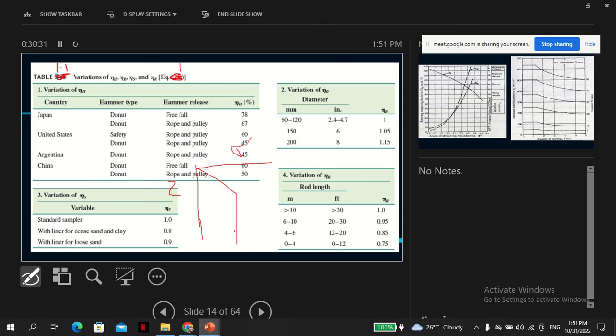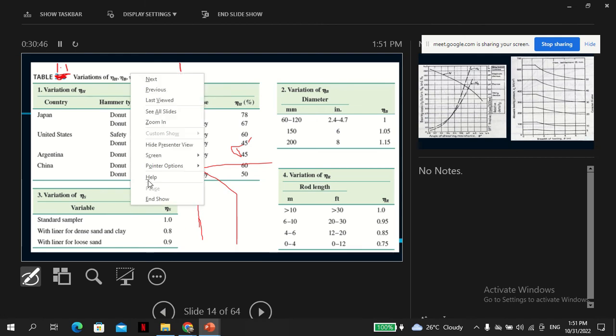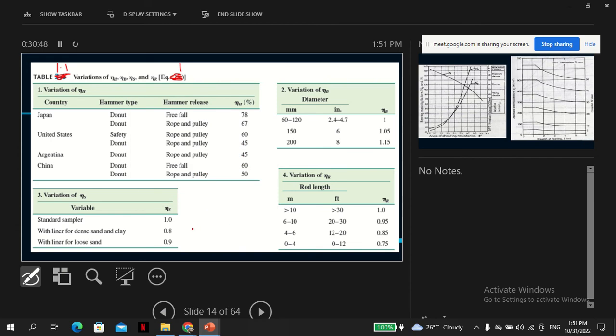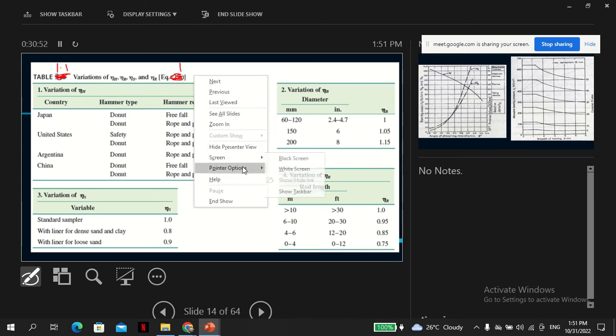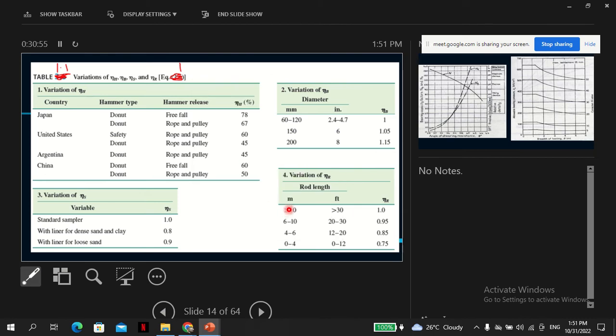So for example, for the depth at 30, if you say 10, 20, 30, you can imagine the soil at that point is under very high confinement, not in comparison to maybe a depth of 10. This gives you a way to look at it. That's the reason why you have to do these kinds of corrections.